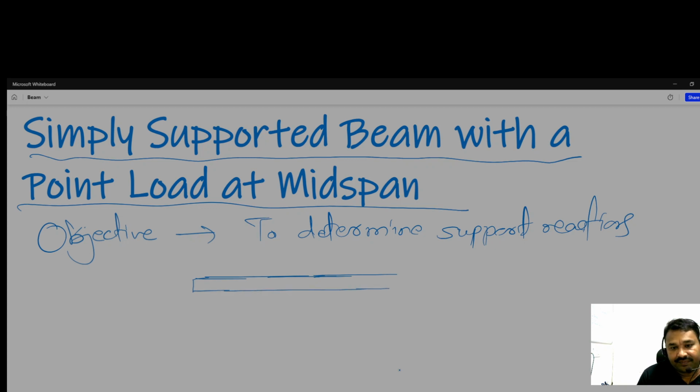So, this is the beam. One end is hinged, the other end has a roller support. You might know that if you remove this roller, there are three rollers you can see here, so it becomes a hinge. But we have to take care of whether our structure is statically determinate or not. That's why, for the three equations, three unknowns are there. Suppose this W load is acting at the mid of length L of the beam.